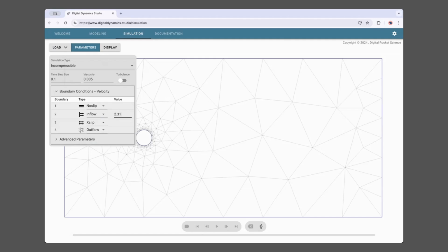You could change it to something else if you wanted to, but usually 1.0 is what we want it to be. We like to use values that are close to 1 or equal to 1.0 exactly, and inflow velocity is one of those things we usually just leave at 1.0. Remember that value was used in the Reynolds number, which is velocity times diameter divided by viscosity. So that's the velocity that we would use in the Reynolds number calculation.